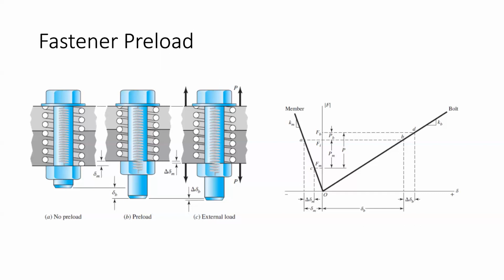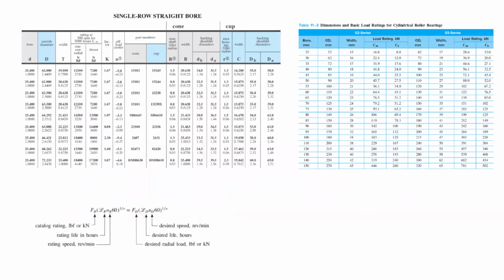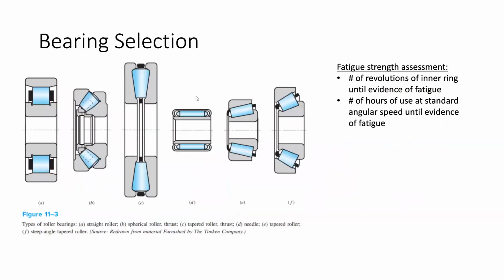A really good example from last year is on the hub, we have what's called a minimum preload that you need on the bearing. So if we go back to this slide, most bearings just aren't drop-in usable. There's some kind of loading requirements or mounting requirements that you need for the system. So for example, we'll use a straight roller bearing just because it's easy. There's usually some amount of tolerance between the rollers and the rings, so there's space between the rollers and the rings.